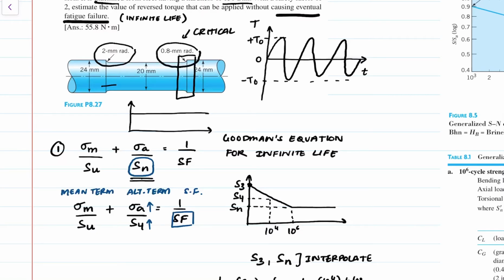But generally, if it's an exam problem, we wouldn't expect you to find the maximum stress at each of those features or discontinuities. Instead, we will make it a simpler problem where we'll have a very extreme radius of maybe 0.5 millimeters versus 10 millimeters. So okay, 10 is kind of unrealistic. So yeah, 2 or 5 or something like that. And it'll be pretty evident which one you would have to choose.